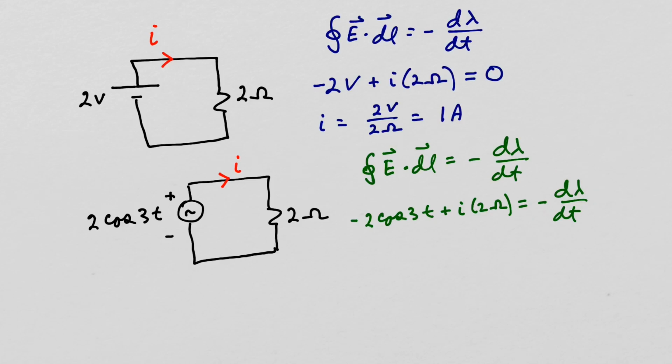If the frequency is low or the surface area here is small, you could approximate this as 0. If these wires are long and the frequency is high enough, this can become a significant term, and we have to treat this as a transmission line.